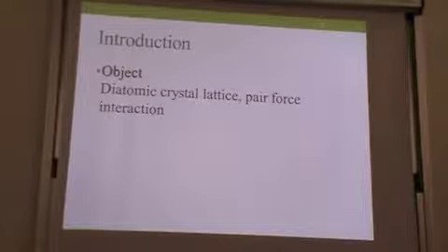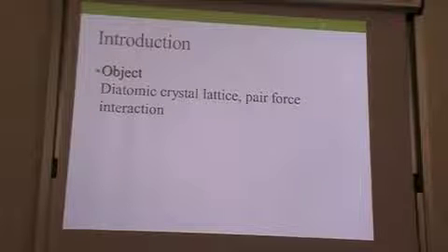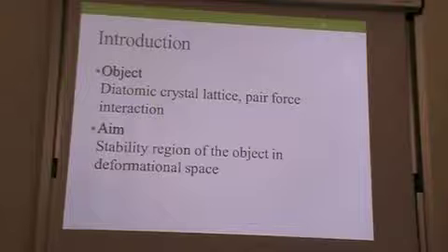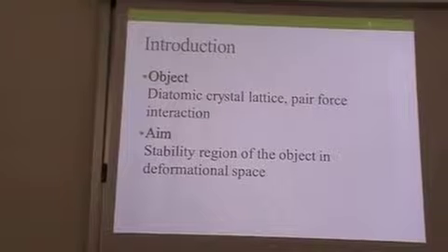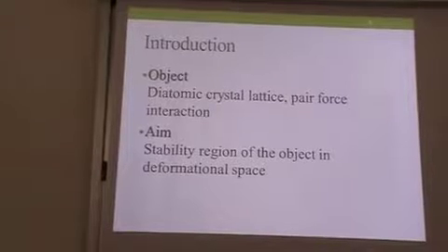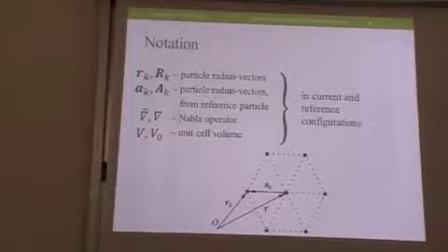In this particular work, we'll focus on diatomic crystal lattices, multilattices, and we'll stick only to the pair force interaction hypothesis to obtain more results analytically. And the aim of this analysis is to get the stability region of the object in the strain space. Let us introduce some notation.